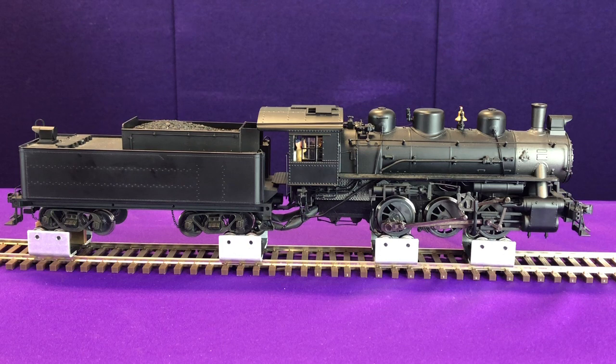Now, that will work, and you can stop the locomotive with the braking rate, and that's set in CV 117, 118, and we'll get to talking about that in just a second. But the next one is when I hit the F12, you're going to hear the train line charge as we go into train brake mode. So when you hear that, you're going to hear the compressor start to cycle more frequently. Because now the compressor is going to automatically work to charge the train line. And again, you don't have to push a separate button to do air compressor slow, air compressor fast, or anything. The decoder is going to do this all based on what you're doing with the locomotive.